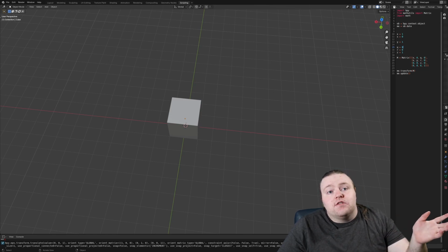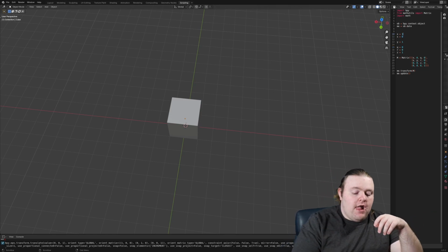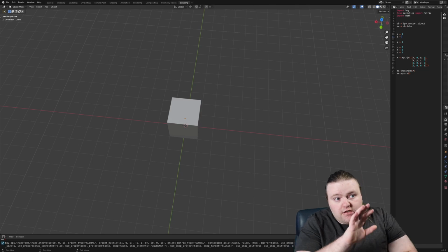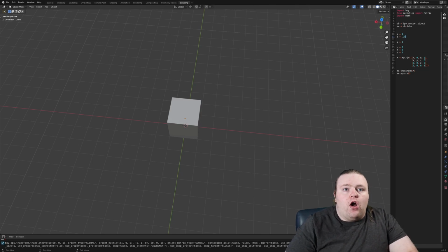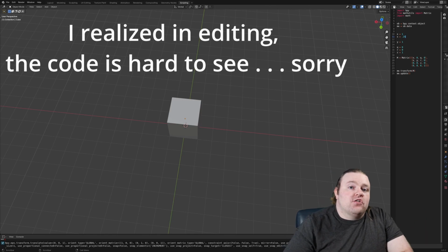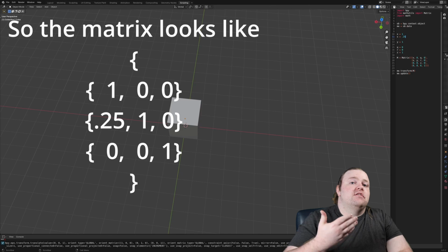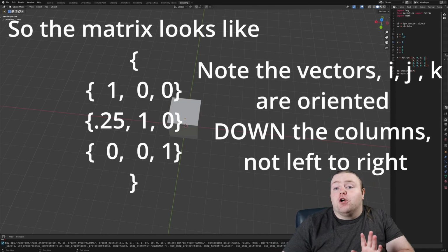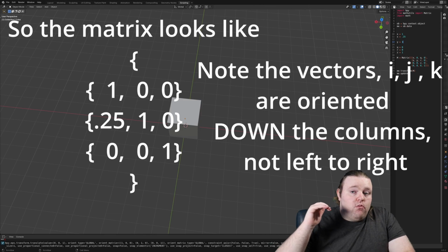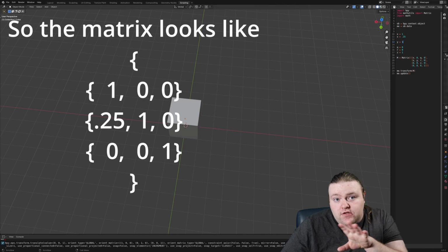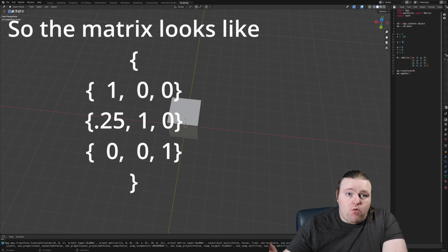So what is happening is, let's say our printer is doing the correct scale of x, but it's skewed. I'm going to be exaggerative so we can see the change, but maybe our x vector, our I hat equivalent on our printer, is actually not 1, 0, 0, but it's 1.25, 0. And then maybe y is perfect. There's nothing wrong with y, so it's 0, 1, 0, or j hat. And then maybe z, for now, is also perfect, so it is 0, 0, 1.